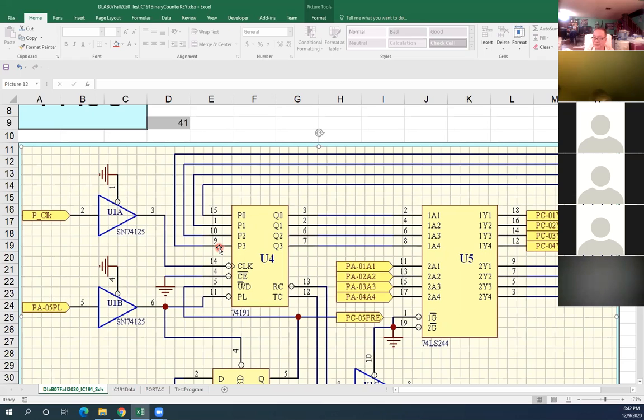Pin 3 of U5? Yes, then you see where they go, right? You keep working backwards. So U3 pin number 5 is supposed to be 0 also. The thing is, we don't deal with the wiring. If you're working in the lab, you have to pay attention to the wiring. So now pin number 3 here can be wrong.